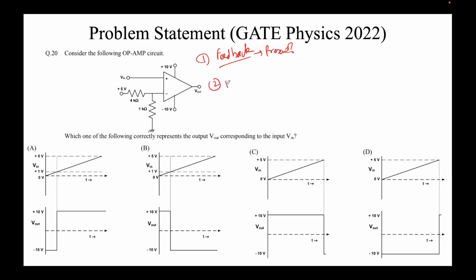Second, if it is present, then is it positive or negative? And thirdly, whether it is negative or positive, you must check the value of the resistances we are playing with. And fourth, it's a good practice to check, in the case of feedback networks, what the configuration is, series or shunt. So it's a good practice to do that.